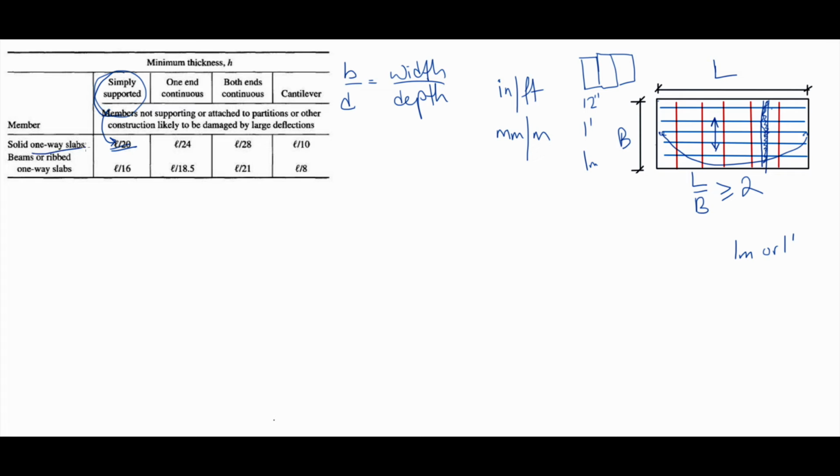We're talking about a one-way slab, which is here, length over 20. It depends on the situations that we explained last lecture, on designing rectangular beams. This is from ACI. There are spacing requirements from the ACI for main reinforcement and for shrinkage and temperature reinforcement.